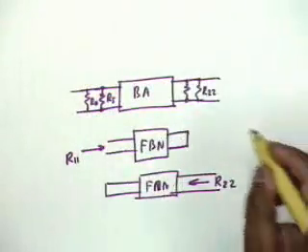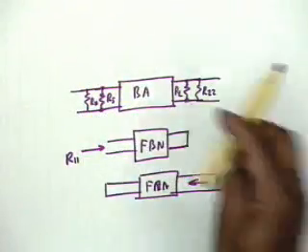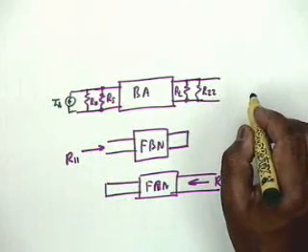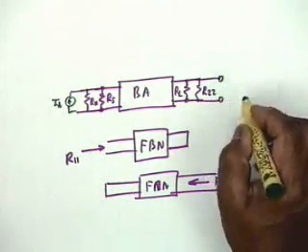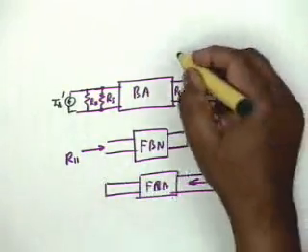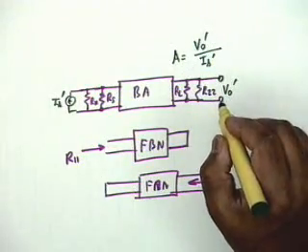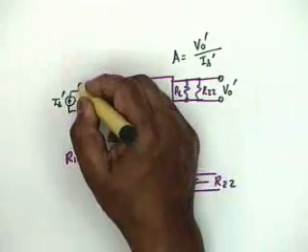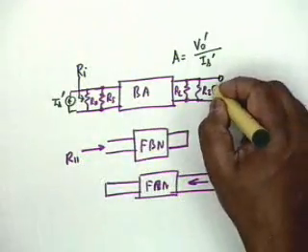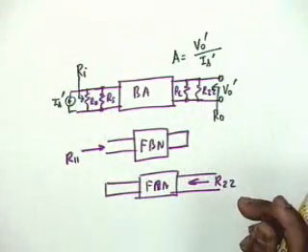In the A circuit, I don't need anything else. That's all the A circuit is. So I drive it by a current source, and what do I do with the output? I leave it open. So this is V0 prime, this is IS prime. And the A now is V0 prime divided by IS prime. Alright? The Ri of the base of the A circuit is this impedance Ri, and R0 is this impedance R0. You see, Ri includes Rs, R0 includes RL.